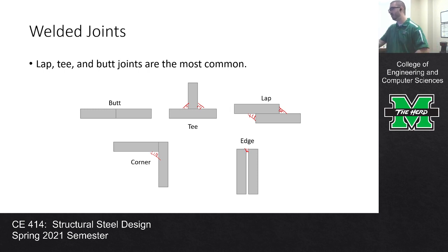Do pipe welds have different naming schemes? You mean like joining pipe A to pipe B? Is that what you're talking about? Well, you're still placing the same type of weld. You might classify it as a groove weld, but you're still doing the same thing. One thing to keep in mind is that we don't do that very commonly in structural engineering applications, because most of the time pipes are used for column sections, and because of the way that we erect them, we can splice those with field splices, and so we usually don't really need to do that.